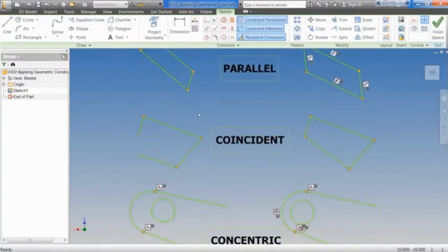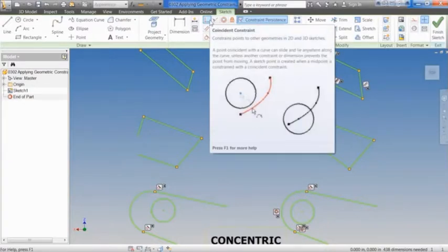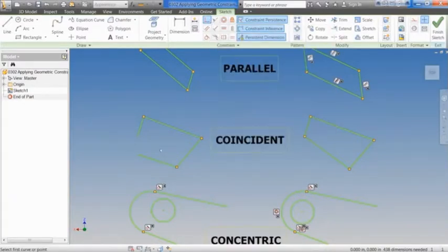Next we have coincident. It's the two lines coming up here running into each other with a little dot. Click on that. I call this one the point-to-point constraint because it gets very hectic with coincident, collinear, and concentric all on the same line, and coincident and collinear look very similar. So I call the coincident constraint the point-to-point. This is what gives you a closed loop.